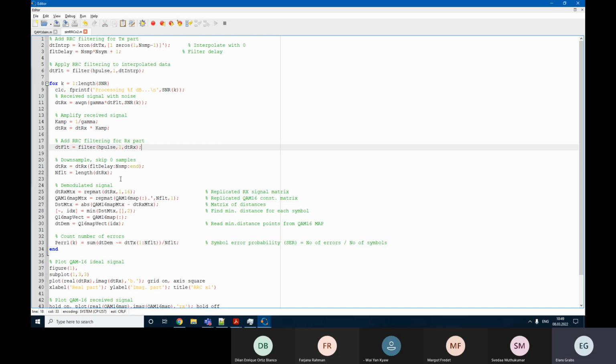Now, however, each of these filters will introduce this delay. It will be twice as much. And accordingly, the first value that we are going to read is going to be here a double. So total filter delay for two filters is going to be twice as much. Well, almost twice as much. This plus one is extra for our real first value, right? So here, pay attention. We need to set this to 2.